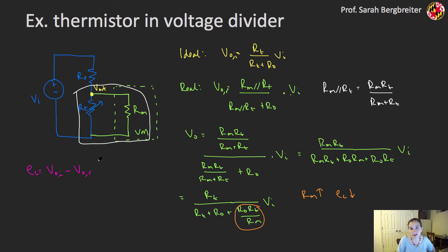So if I plug actual numbers into this for the resistances, I can get some sense of what that loading error might be. So if I want to solve this loading problem, really what I need for whatever touches my sensing circuit, whatever is providing that interface, is a really high, approximating infinite, input impedance.